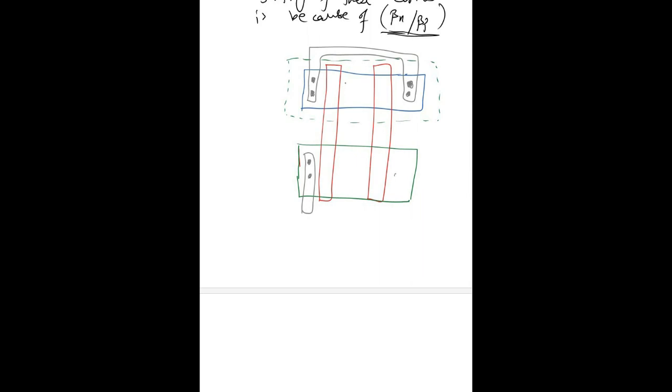So we have contacts at this point and at this point. This represents our out. These are our inputs VA and VB, this one is connected to VDD, and this one is connected to the ground terminal. So this was our overall circuit for our NAND gate.